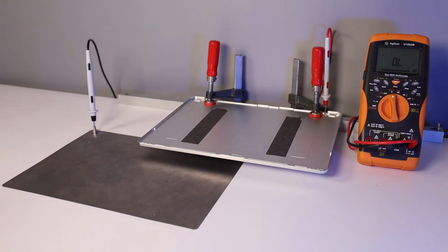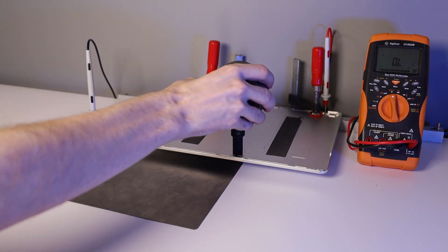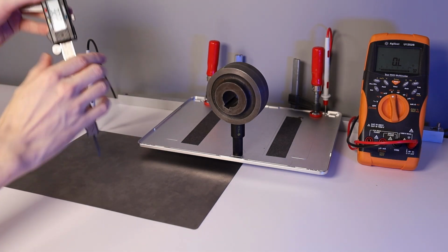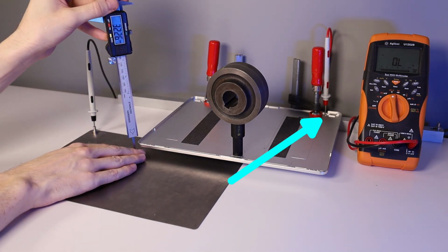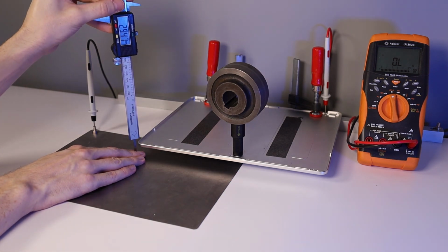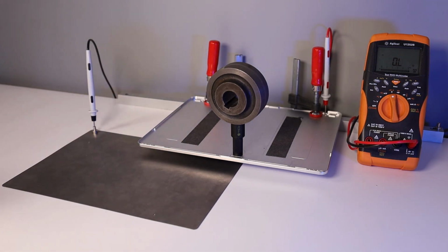Alright, speaking of the real-world measurements, this is the highly sophisticated measurement setup we'll be using. It consists only of 2 clamps to mount the lid on a flat surface. Sandwiched in between there is an aluminum profile that just acts as a spacer. The multimeter in the frame is set to continuity mode. One lead is attached to the part that we want to measure, and the other lead is attached to a small steel plate underneath the part. Now, as soon as the digital caliper makes contact with both the steel plate and the aluminum part, the multimeter will let us know with a beep when it's time to read the scale on the caliper.